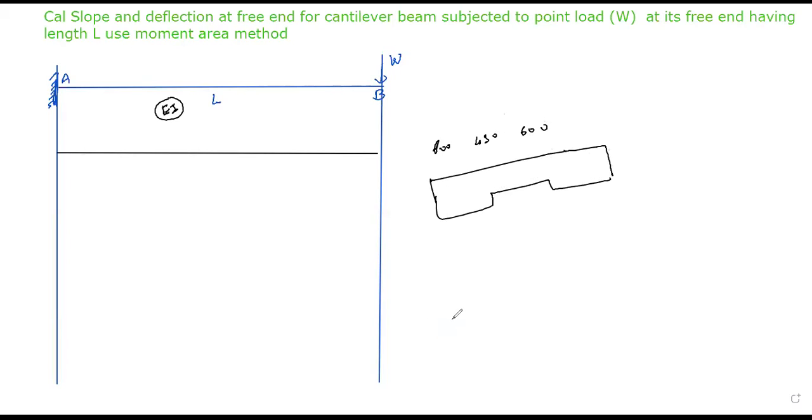Okay, so now I is nothing but your moment of inertia. E is your material property. Whenever your depth varies, E does not matter. That is a constant because it is a property of the material. But I is your moment of inertia, and that is the rectangle section moment of inertia, BD cube by 12. Yes or no? If your depth varies, your moment of inertia will vary. Okay, so EI is the effect of the cross-sectional dimension on its moment. Okay, how it will be applied, we will see in the next example.